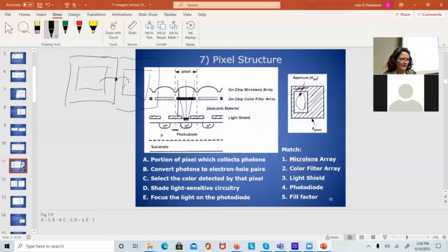And he was doing all kinds of lenses on the camera and color filters. So instead of getting a grayscale image, you could get a color image by putting a lens that would only pass green light on one pixel, red light on an adjacent pixel, blue, and then interleaving those. So the pixels were small enough that you couldn't see the red, green, blue.